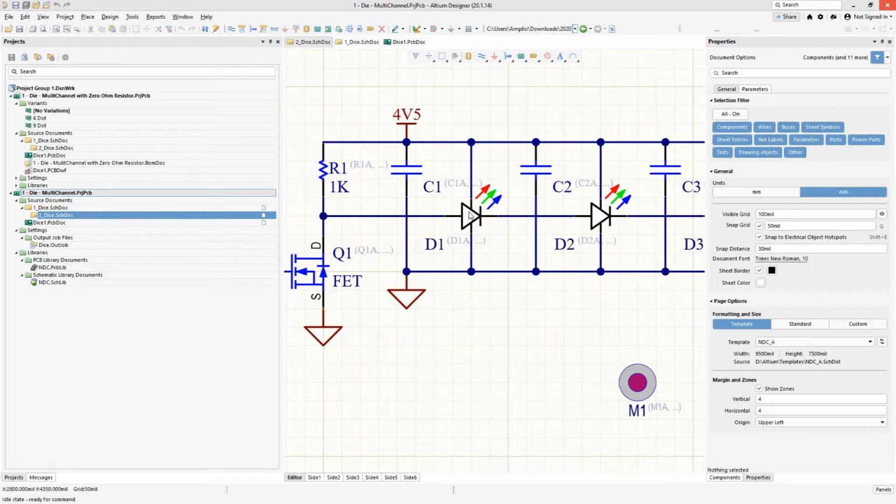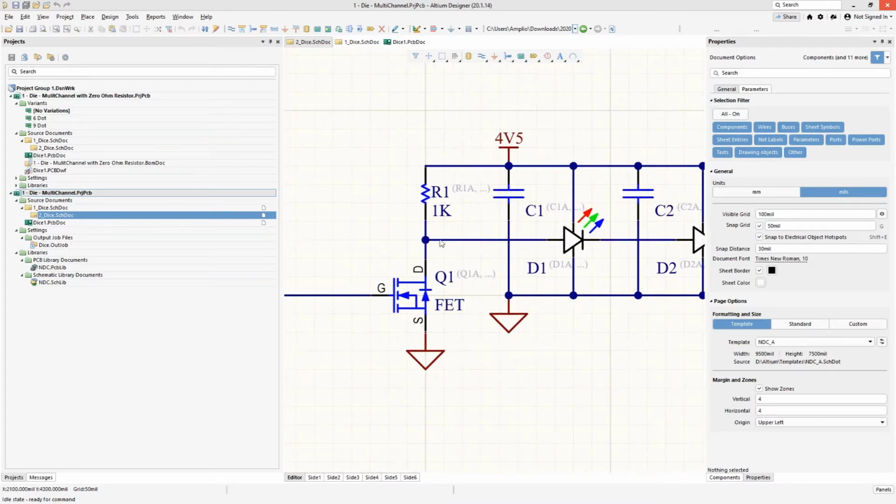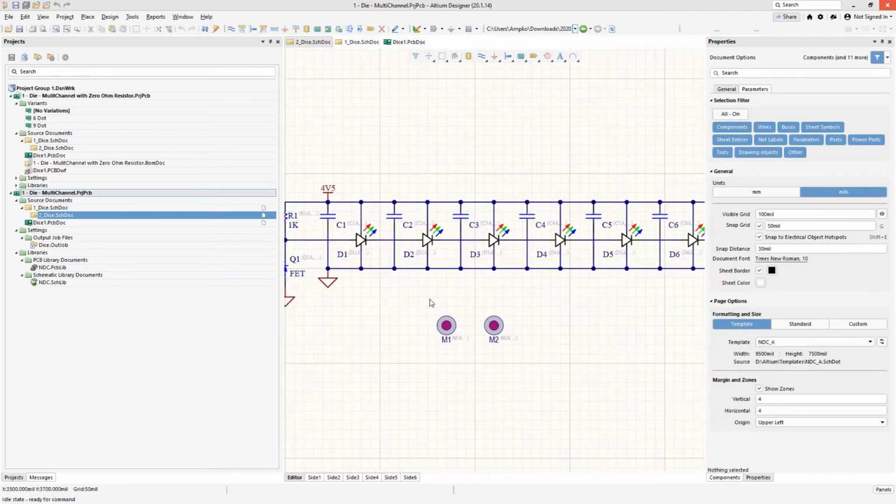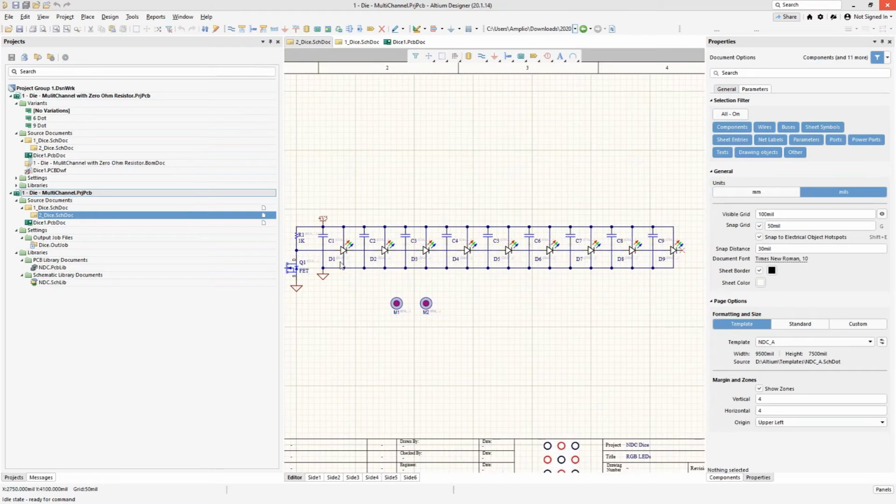So with that, you can tell it what color, and you can also determine which one should be turned on and which one should be turned off. It's all done through basically passing this information through on the single line. Now, obviously, we're using a FET over here to turn this thing on and off, but the control of that is coming from the PIC processor. So that gives you an overall idea of what's happening here, and there are 9 of these LEDs on each side.